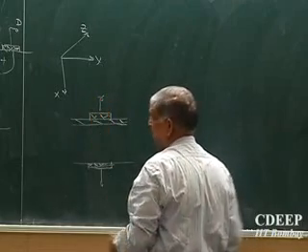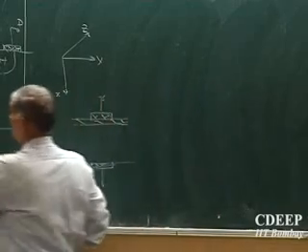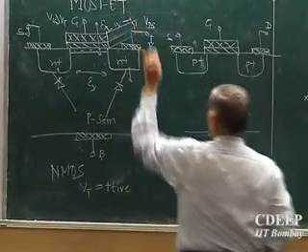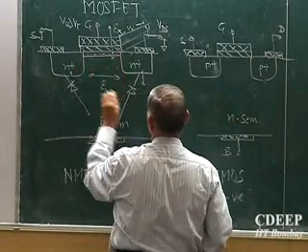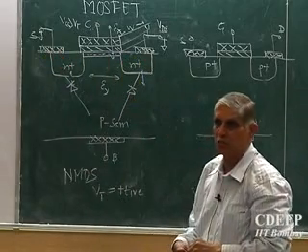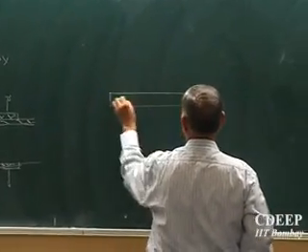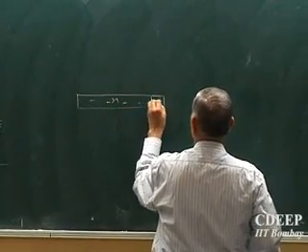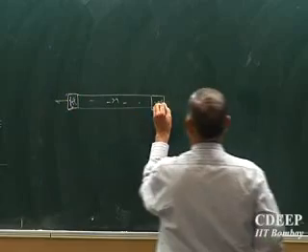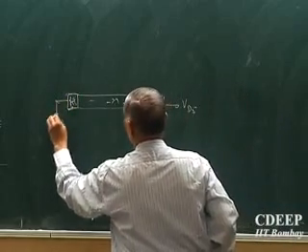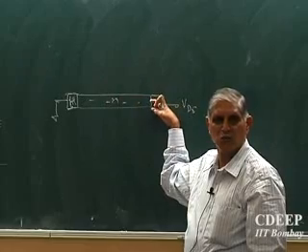Now in this case, there is a difference between this case and this case. If this is grounded, this replicates this. But let us say if I apply a plus value here, now you can see there are electrons here, and if I apply from source to drain a voltage VDS, this is looking like me. You have a channel which consists of electrons, N type. Then there is this N plus, source and drain, both N plus. I am applying VDS, and this N is essentially decided by Ex, but right now the number is known. For given VGS, this N is known to me.